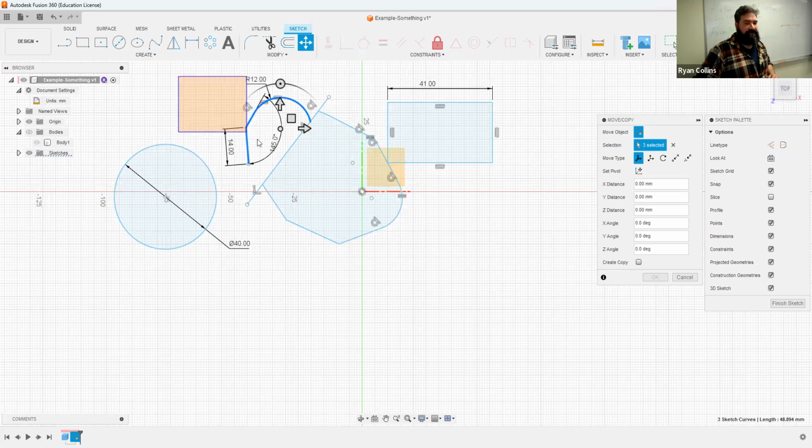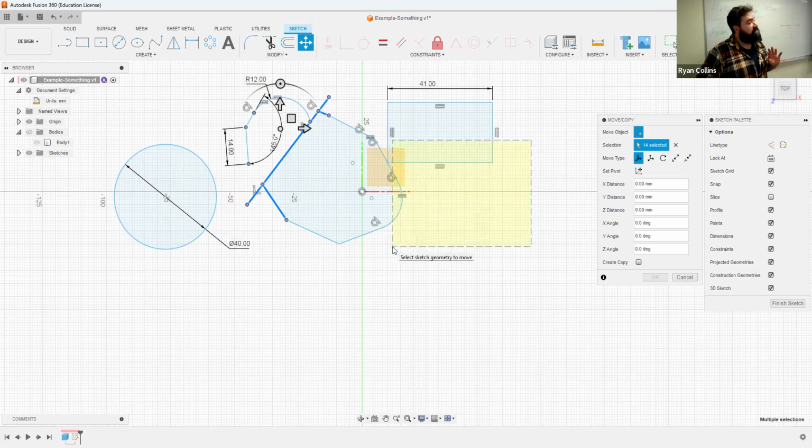If you click and drag from the left, dragging right, the blue box in orange, it will only select what is completely within the box. So those lines were, but the whole thing wasn't. If you drag and select, or select and drag from the right moving left, blue dotted line with yellow inside, it will select everything that box touches. Now, that wasn't the whole thing, so it's selecting just chunks of that line.